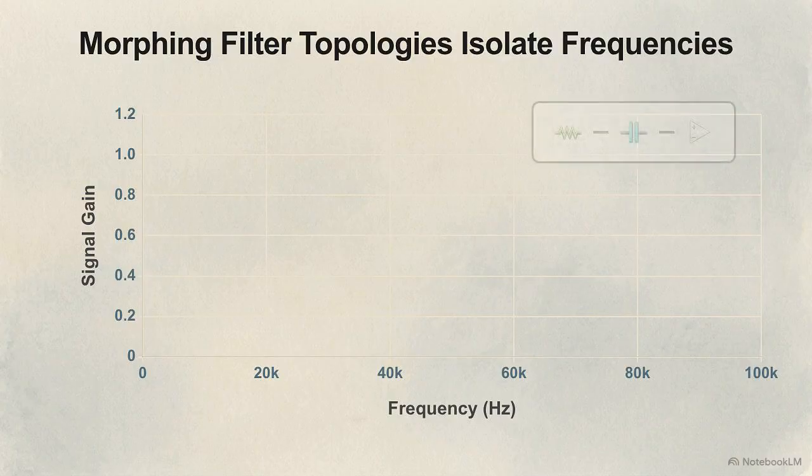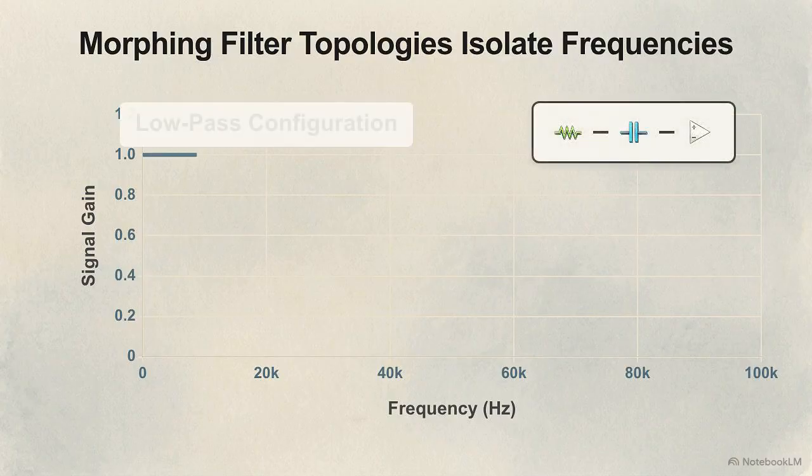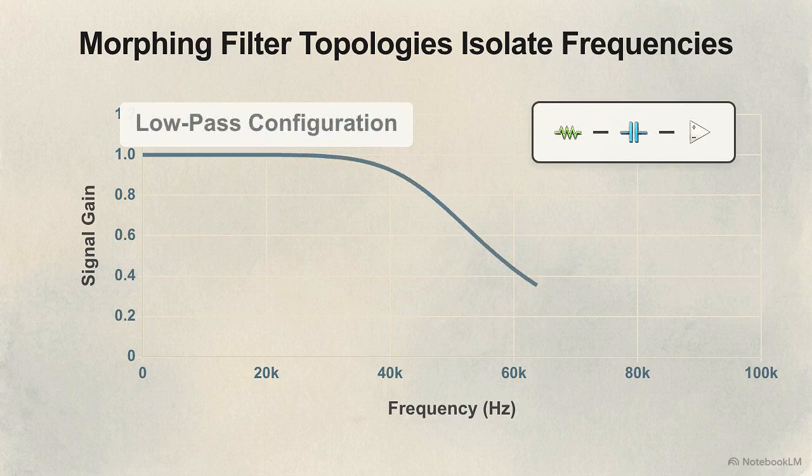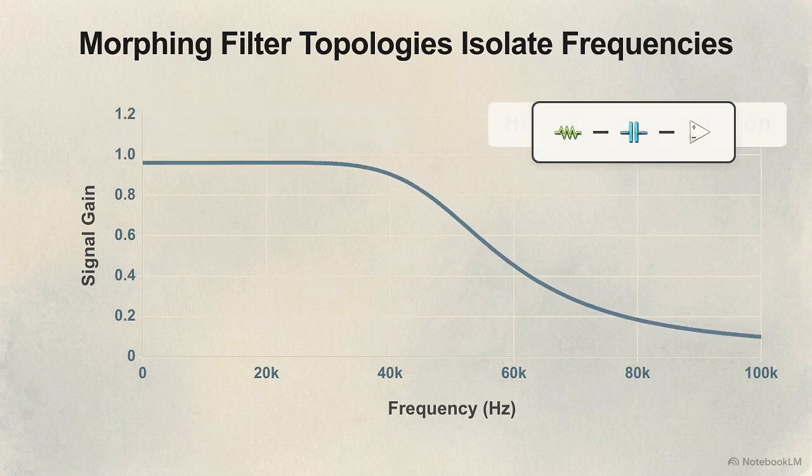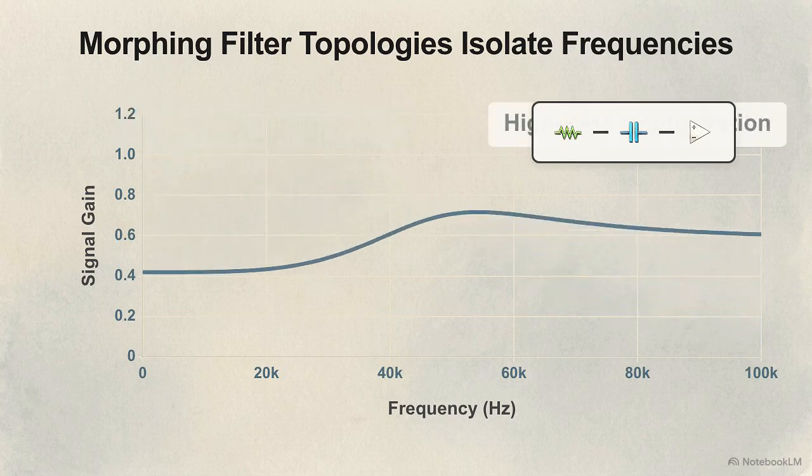This Bode plot shows the frequency response of a Butterworth design. It is engineered to achieve a maximally flat passband, meaning all desired low frequencies pass through with absolute uniformity before it sharply drops off to slice away unwanted high-frequency noise.